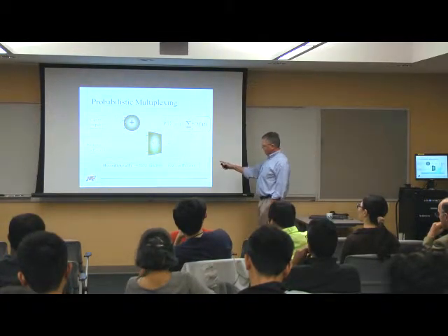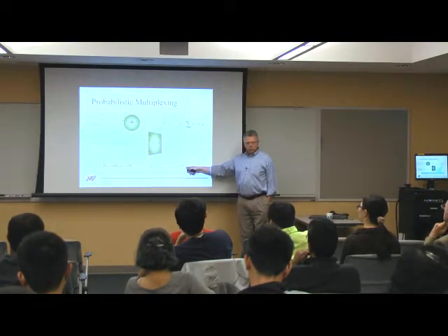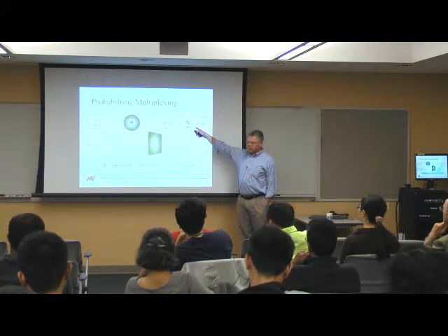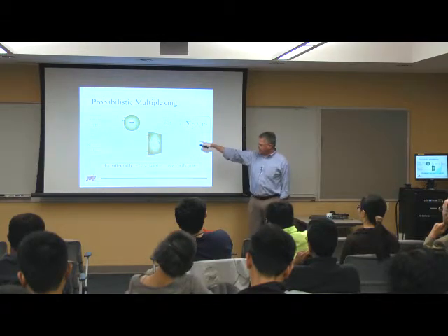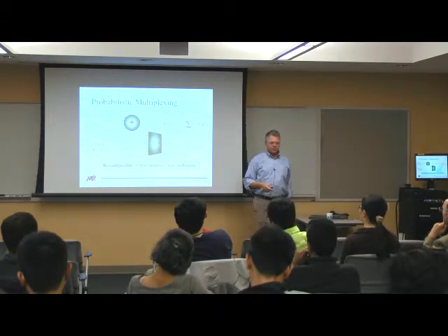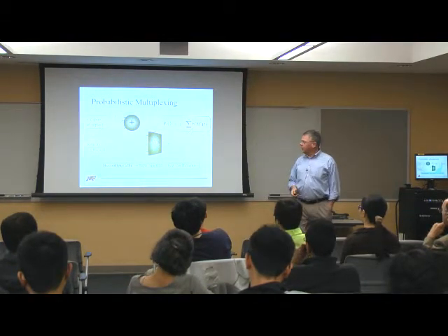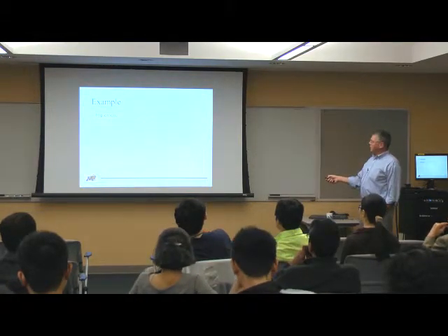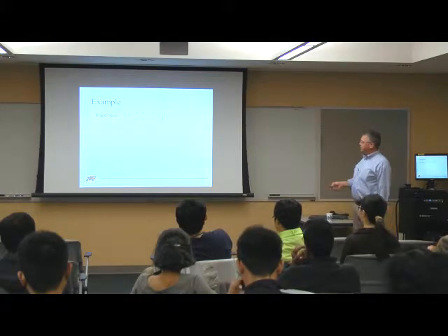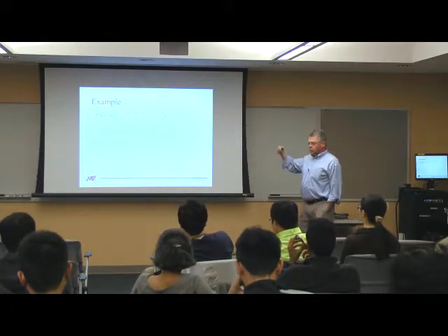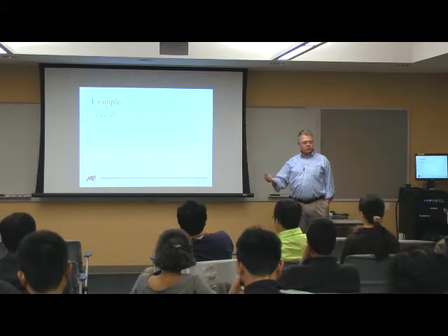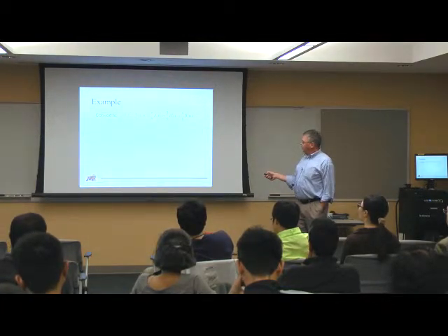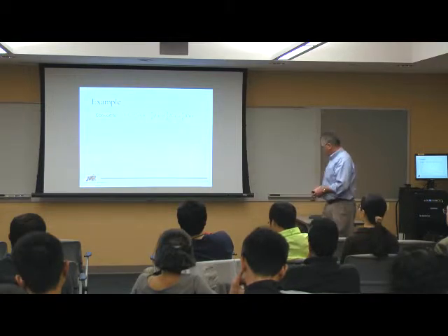So as an example, before I do that, let me point out the nice thing about this from a hardware designer's point of view: this is very reconfigurable. All I have to do is put in new coefficients, and this exact same hardware can compute a completely different function. Okay? So as an example, here's the polynomial that I want to implement. F of t, 1 over 4, 9 over 8, and so on. I go through my conversion to a Bernstein polynomial, and I end up with this polynomial. Notice all the coefficients are between 0 and 1.